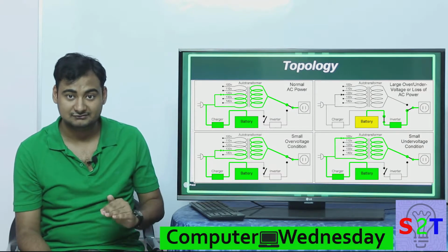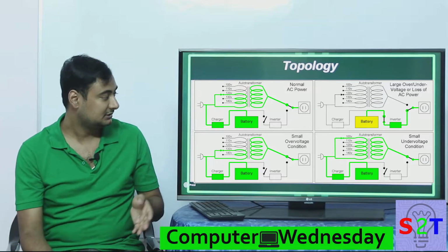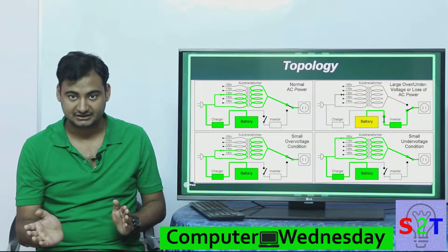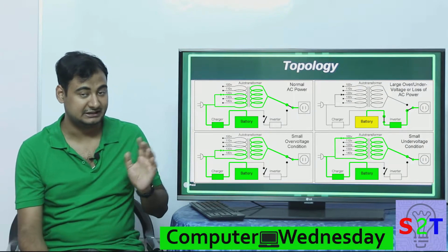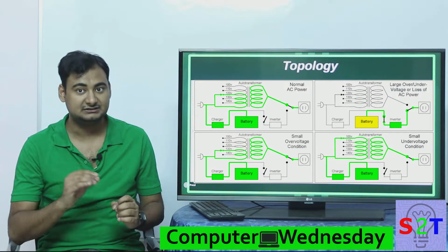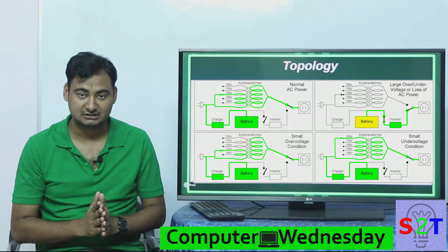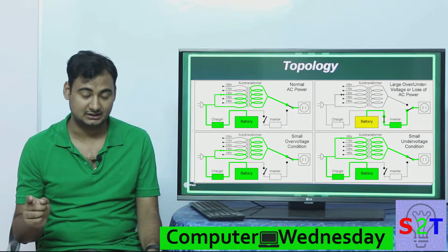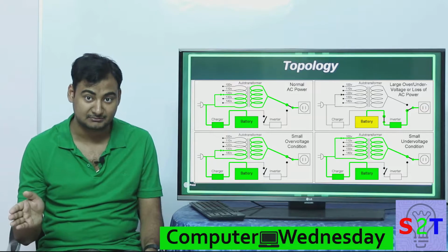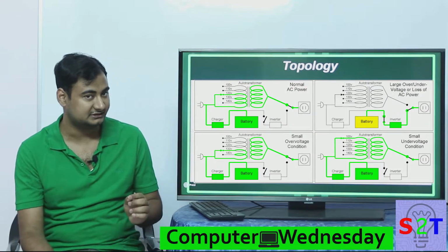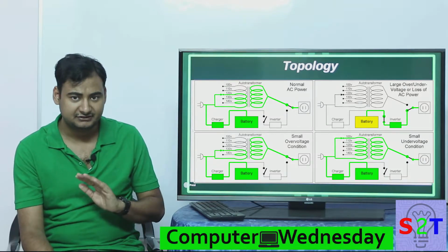Now let's say you have over voltage, your grid goes over volt, and it will again disconnect the system. Then it will use the battery in that while, because any of you who have worked with stabilizers know stabilizers take a while to change. So in that while, just so your computer does not shut off while it is trying to change, it switches to UPS mode. Basically you are running from battery power. You might hear it basically cut. You might hear this sort of sound from it.